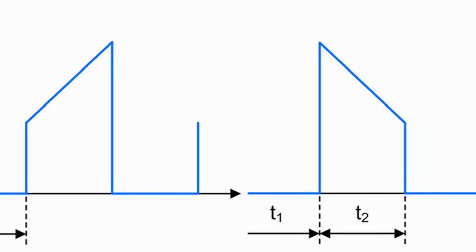And one last important observation I want to make is about the current waveforms in the transformer. If you go to the VI's Power Topologies Handbook, you'll see these wonderful graphs that show current through the primary and secondary winding, right? So you can see the current ramping up in the primary side, and in the secondary side, it actually is ramping down during the energy transfer phase, AKA the discharging phase, if you want to think about it in terms of the buck or boost converter.